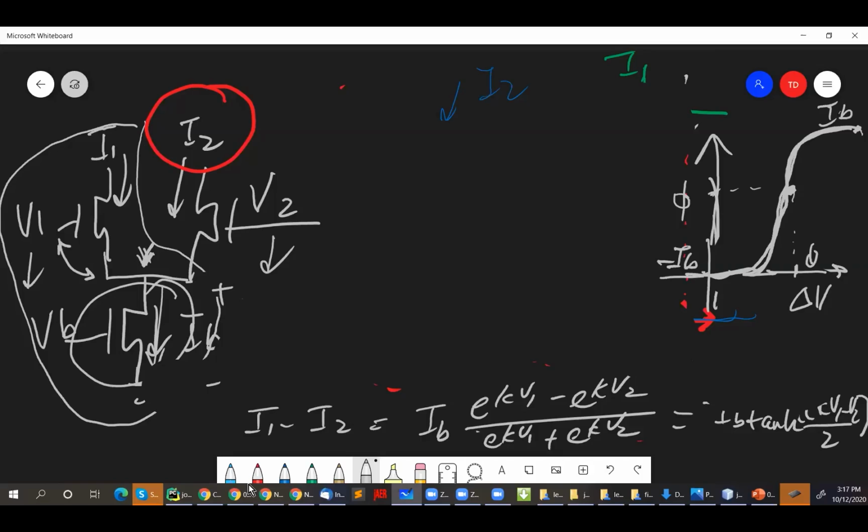For most cases, you would set V1 and V2 to voltages high enough that saturation is guaranteed, and then use above threshold equations for I1 and I2. Otherwise it's too crazy. Then you should run SPICE or write some real program that will bring in the right equations depending on what the currents are and what the VGS is.